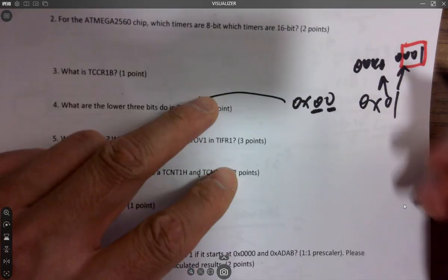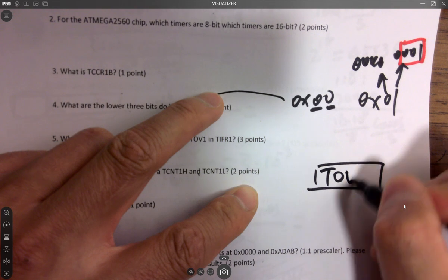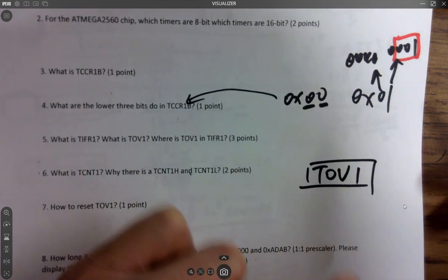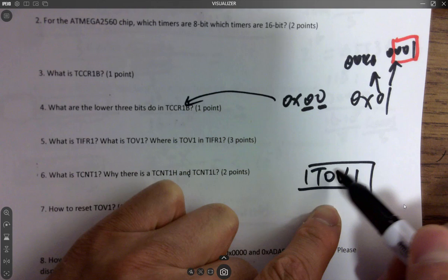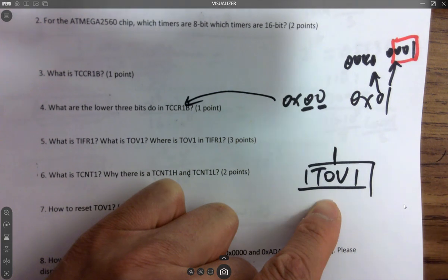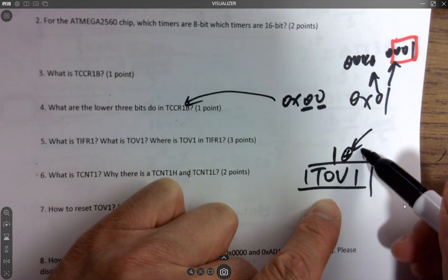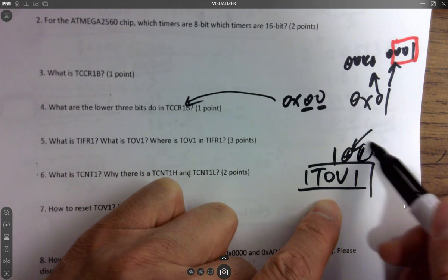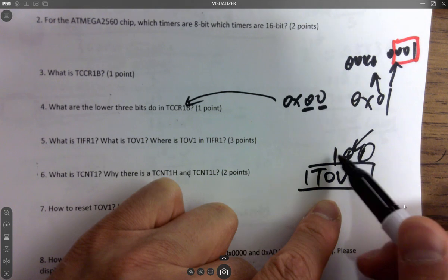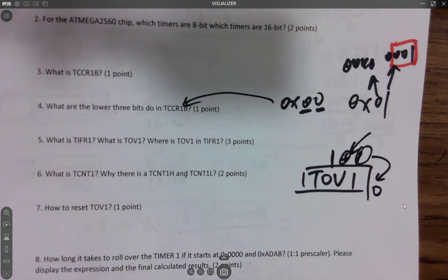Whenever TOV1 finishes, it has a 1 here. So when you are doing that assignment to this bit, it's basically doing XOR logic. So this is your 1, and the 1 will be XORed with the previous 1, eventually resulting in a 0 being put into this register as this bit. Because 1 XOR 1 is 0, right?